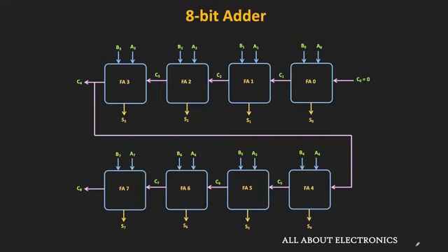Now in this adder, all the input bits, the A's and B's, are applied simultaneously to all adders. But here, each adder has to wait for the valid carry from the previous stage, and that limits the speed of the addition. So let us see how to overcome this problem.